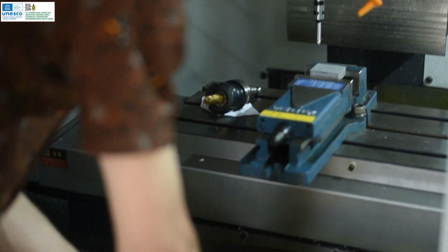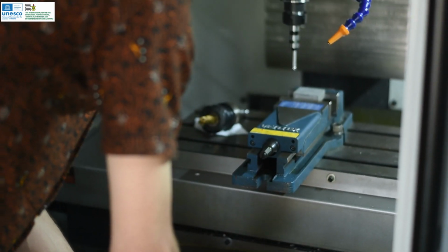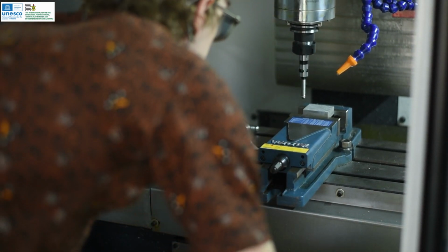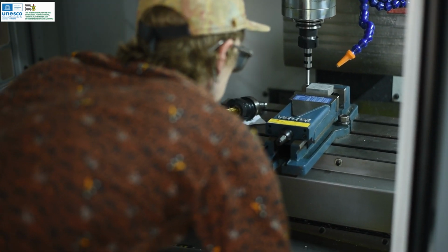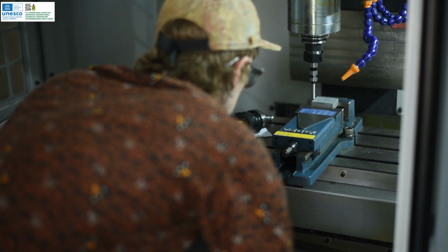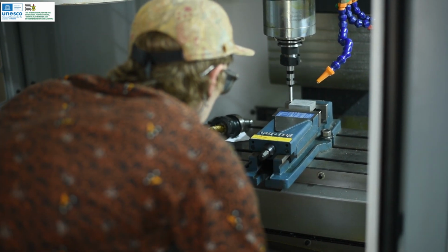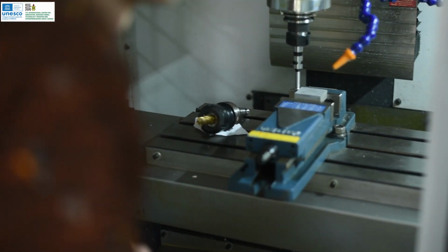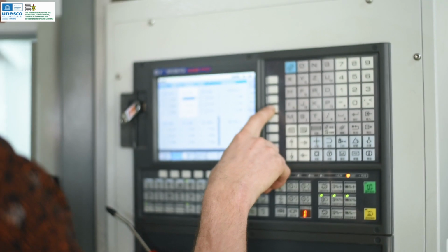We'll move over in X until we're safe. Down in Z until the ball is below that surface. In X, we're going to approach very slowly, our smallest increment, until that touches. Once that edge finder ball touches, you can move off by one click so it stops beeping at you. Hit measure input.